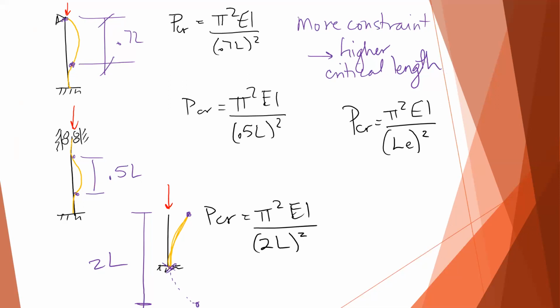And actually, let's be very careful with that. Maybe it's not that there's no shear stress, there's no horizontal reaction. So the more curved that member becomes, in this region here, if this member becomes curved, what I'm saying is there's no horizontal force, but that vertical force might start becoming more and more shear as opposed to axial.